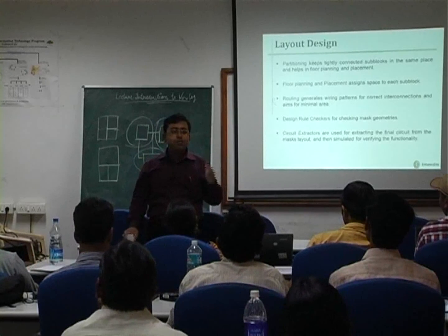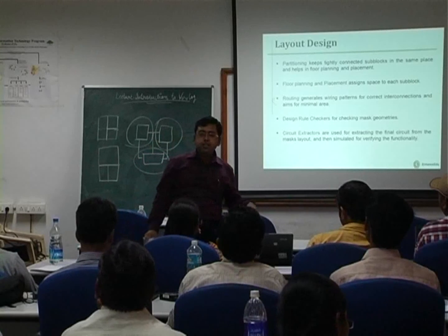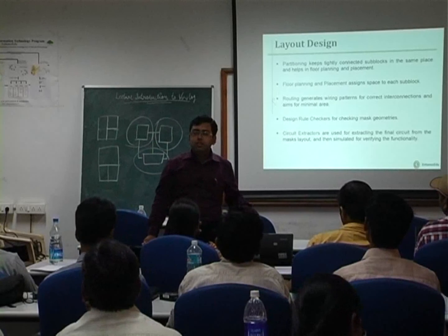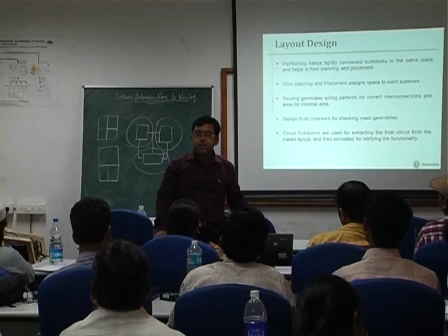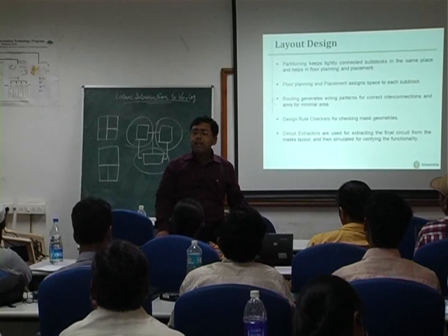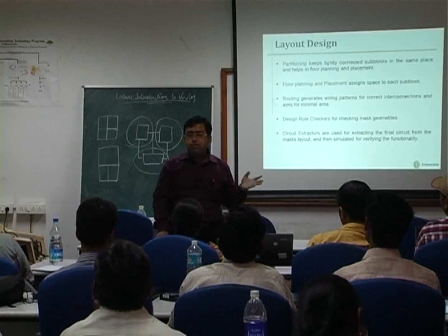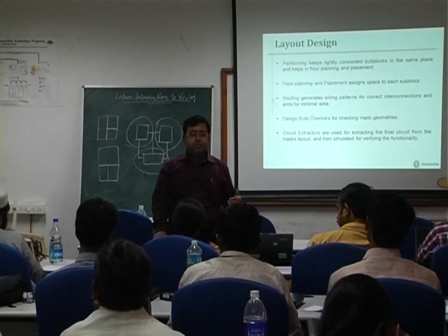But when it comes to the layout design, you have to take into consideration the effects of these parasitic resistances and capacitances of the interconnects, and therefore if you do the post layout simulation, you will find that your results are different.